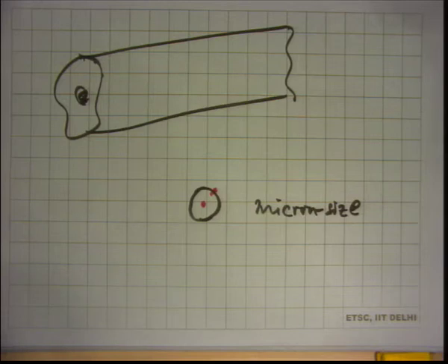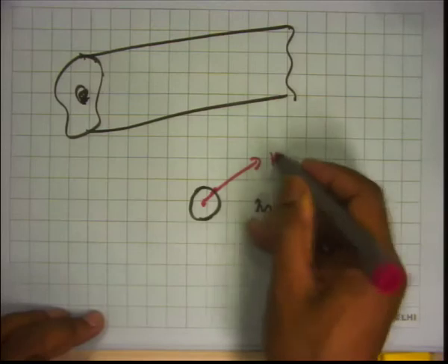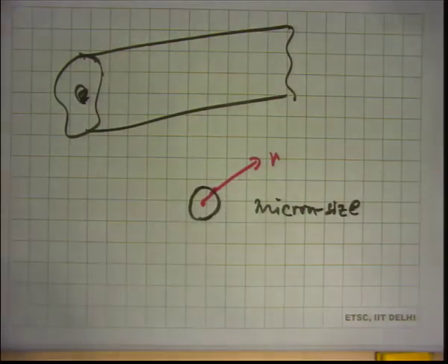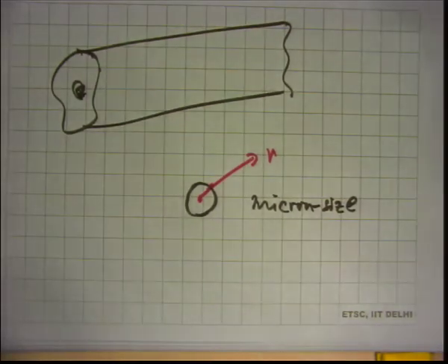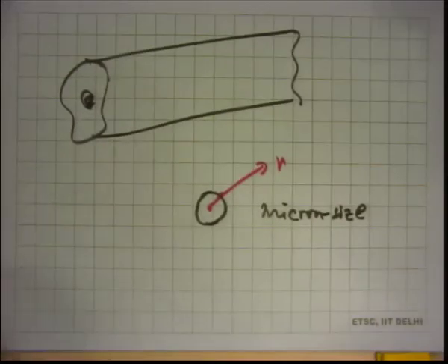That temperature will increase as combustion proceeds. Okay. But it's uniform. Uniform means spatially, like radially. If you take the radial coordinate, the temperature doesn't change with the radial position. So that's a good assumption that you make. So here, in the log case, you have drying, devolatilization, and char combustion taking place sequentially in different layers.